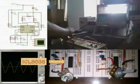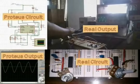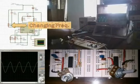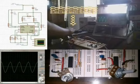We used ICL 8038 to produce the sine wave. Initially we designed Colpitts and Wien bridge oscillators, but they don't operate well in the low frequency range of 300 to 3400 Hz. So we opted for that IC. Besides, it offers the opportunity for changing the frequency range, which was not available with those designs. The 10K pot connected between pin 8 and VCC plus 12 volts mainly controls the frequency.